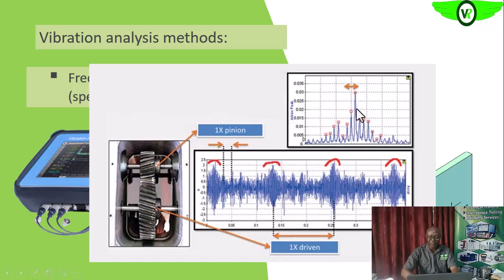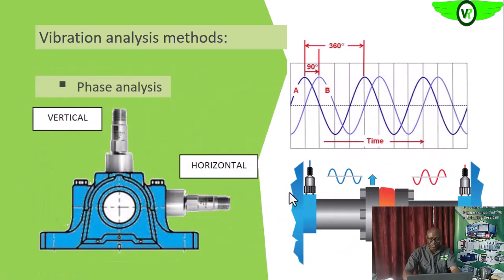So it is now left for us to look at the frequency and see what forcing function is actually operating at this frequency. It could be the bearing frequency, or the gear mesh frequency. We have bearings here too, which could be contributing to the overall vibration that we are seeing. All of this will help us to determine what is actually causing the problem.